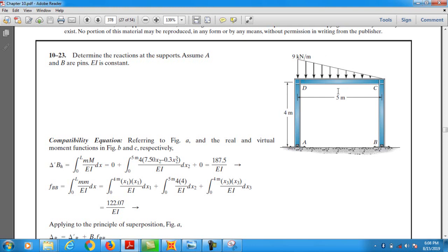So select this beam. Go to the assign menu, frame loading, select distributed loading, and once you select distributed loading, make sure self weight multiplier is 0, and just use the spacing option. Absolute spacing option, and you insert a 0 distance, and in load you insert this value.